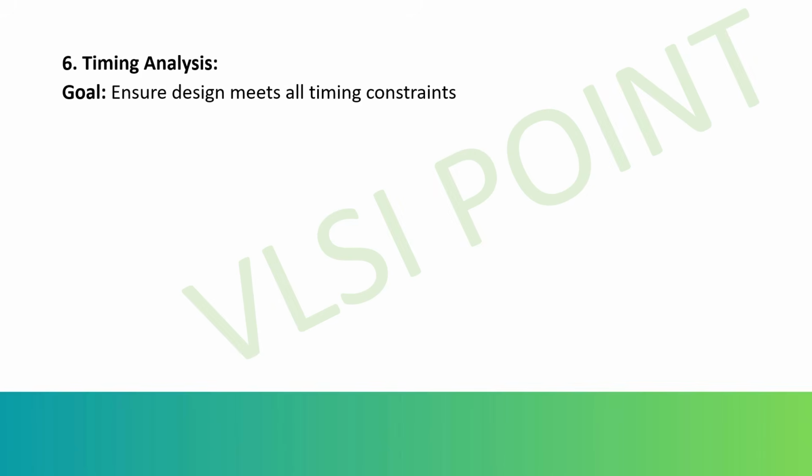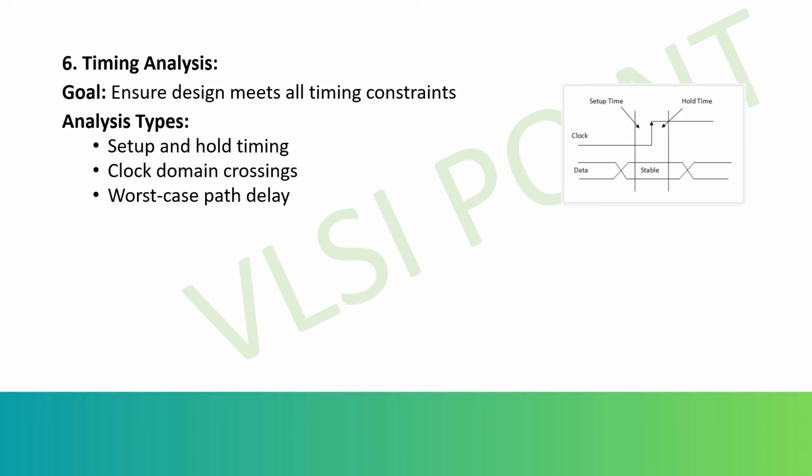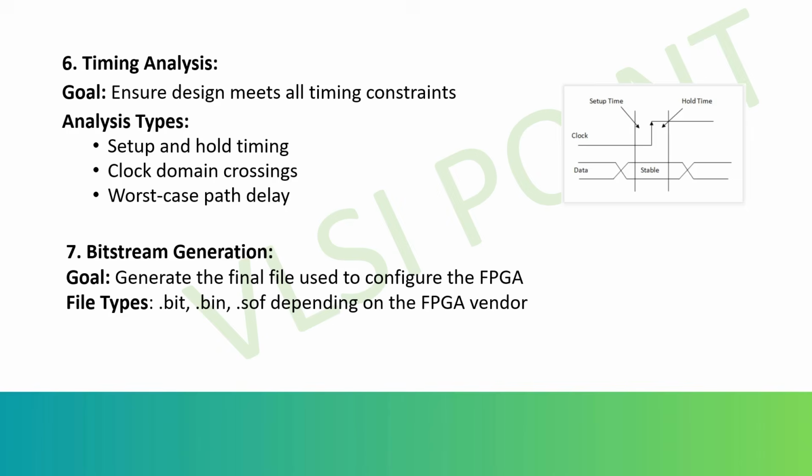Then there will be timing analysis. So it will ensure all signals meet setup and hold time requirements. So check for clock domain crossing and maximum frequency. So you can see here how the setup time and hold time is defined and where the input signal must be stable. After timing analysis, there will be bitstream generation.